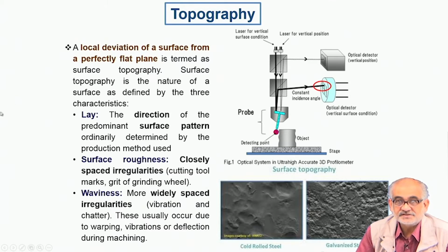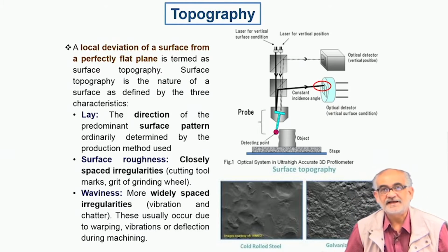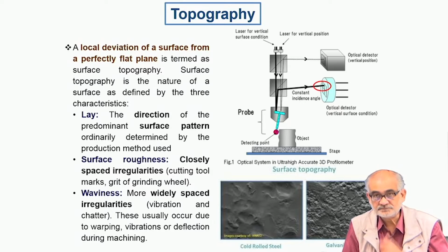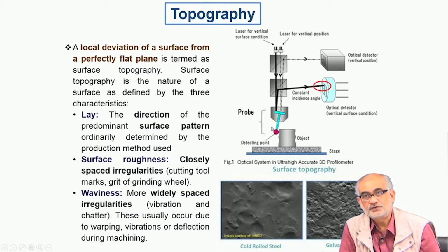So, whenever we have such topological or topographical variations and we need to measure them, then we employ one of these profilometers, which could be a contact type like here, or a non-contact profilometer. In a non-contact profilometer, we generally follow the reflection profile, and the surface, if it has certain levels of waviness or roughness, will definitely show different kinds of contour.